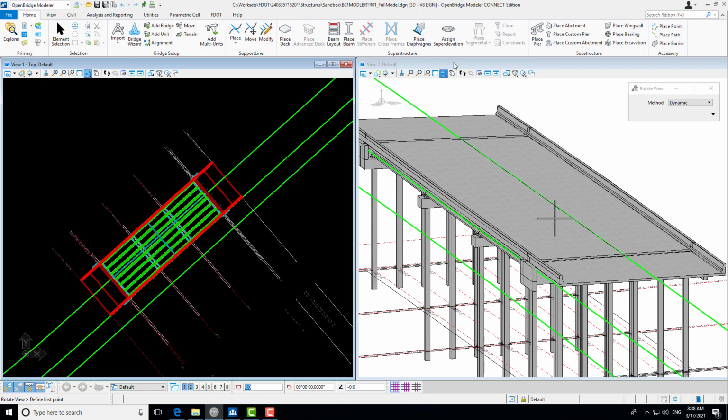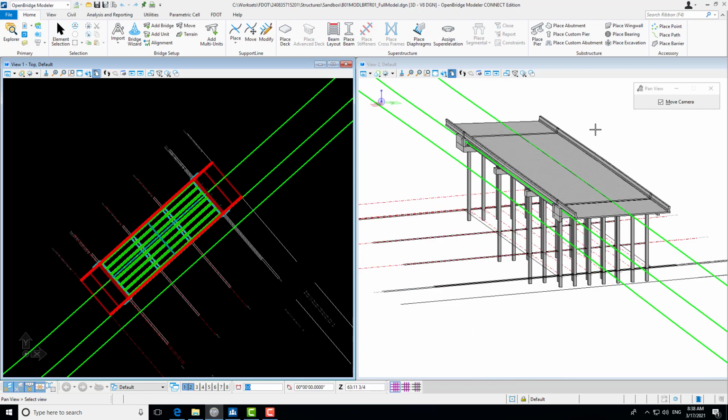I also wanted to bring up a little bit of the background of model-centric workflow. So the model-centric approach in this manual is a little bit different. It's a little bit of a shift away from what we all are familiar with, our traditional CAD and developing our details for our plan sets. So instead of creating these separate views in 2D spaces and stitching them together into a plan set, we're creating this 3D model, which will be the central repository of data that will be used and linked to other activities, including plans generation, 2D plans generation.